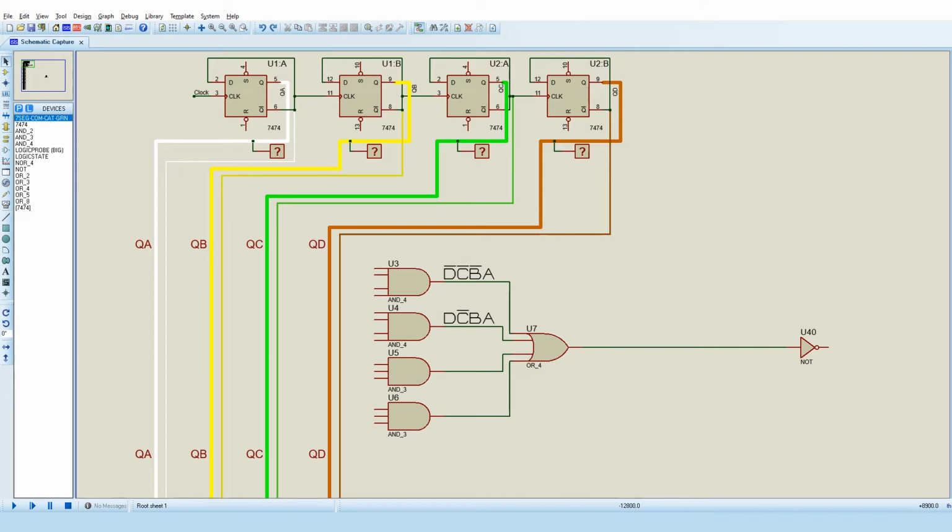And these are the 4 binary expressions that we worked out earlier for the value of not A. So we just wire them up. So the output from the OR will be not segment A, because we worked it out to be not A, equals all that.